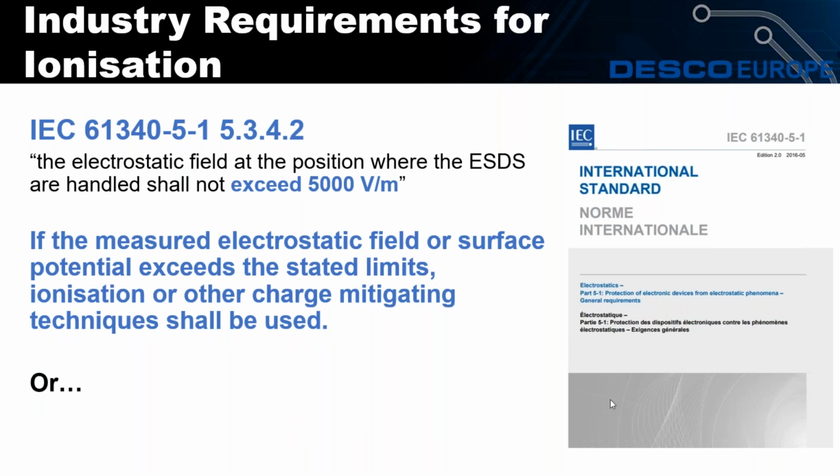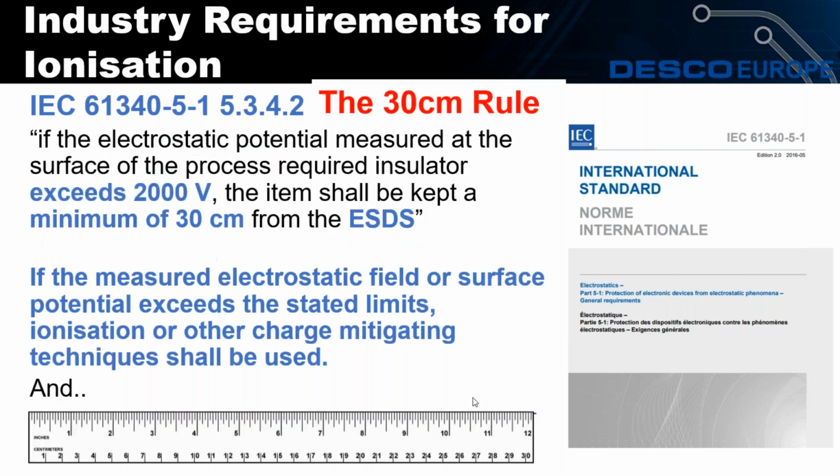Before we deal with specific items that might carry a charge, first of all, we need to make sure that the environment doesn't have high static voltage. This is especially possible in environments that are controlled to a low humidity. Most places now will be air conditioned, and therefore the humidity is very low. So we need to make sure of that in the first instance.